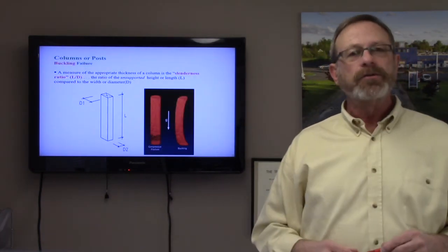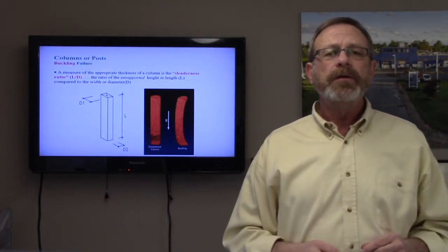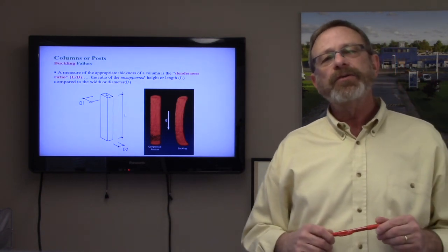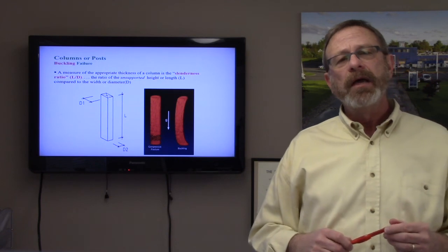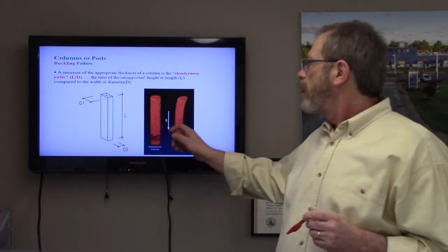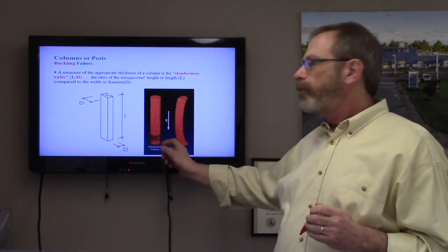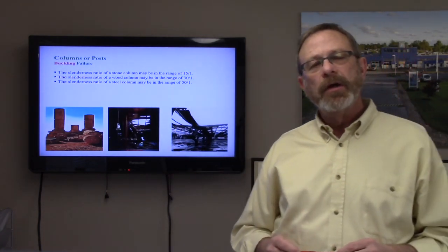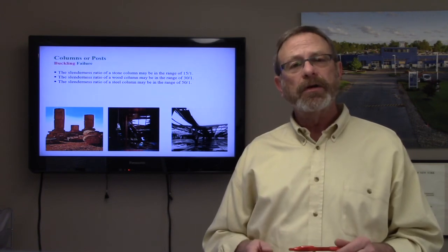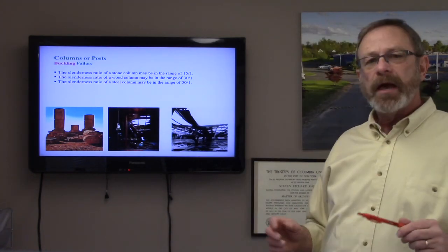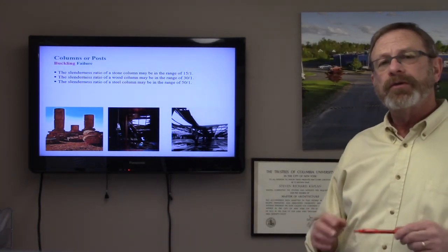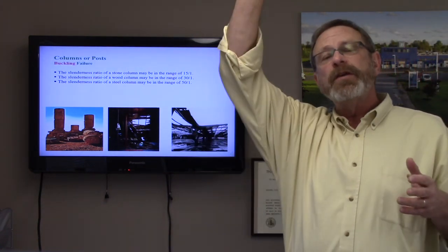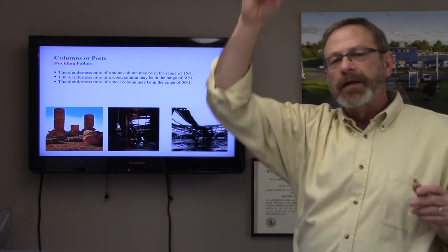So we hope that those stresses, when relieved, have that object, because it is elastic, return to its original position, state of rest. So when we talk about columns, we need to discuss the slenderness ratio. It's the means that we use to assess the strength and stability of a column, and it's expressed as a ratio of length, L, over D, diameter. It's important to us as designers because we want to be efficient in the construction of our skeletal structure. So we can have steel columns which, according to the slenderness ratio, need be only 1 foot wide to go 50 feet tall. That's a good height.